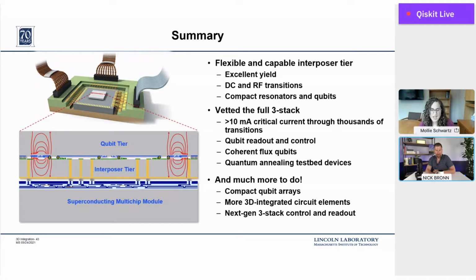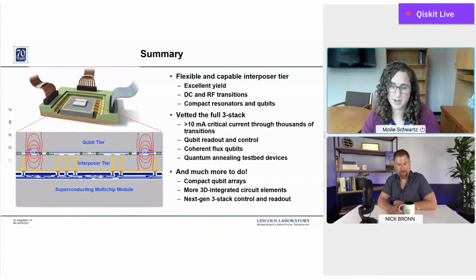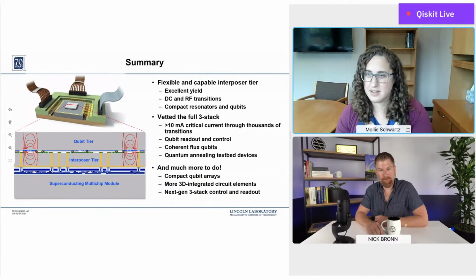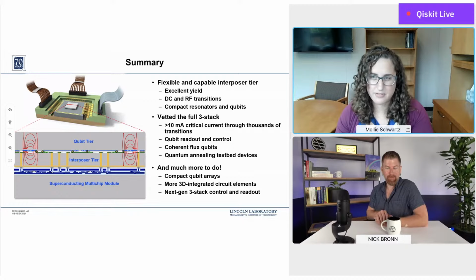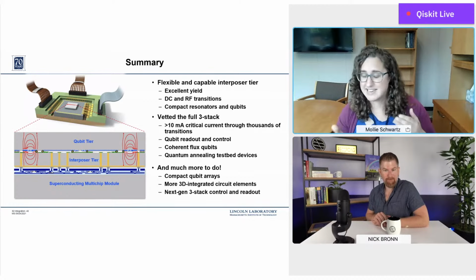Yeah, there are always things that we can learn from classical electronic processing. And one of the really great things about the Microelectronics Laboratory is that it does CMOS processing, it does superconducting electronics, both classical and quantum. So there's really a great depth of experience and built up knowledge that exists in the facility. But there are differences, right? You can't use normal metals in a superconducting qubit system because you inject quasi-particles into your qubits and you destroy all of the hard work that you've just been trying to do to create coherence in the system.